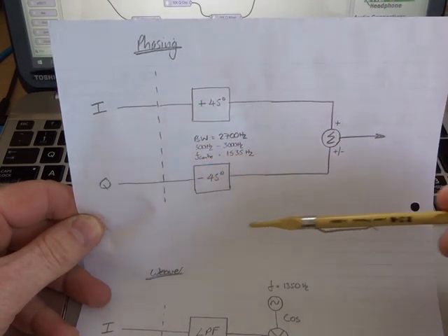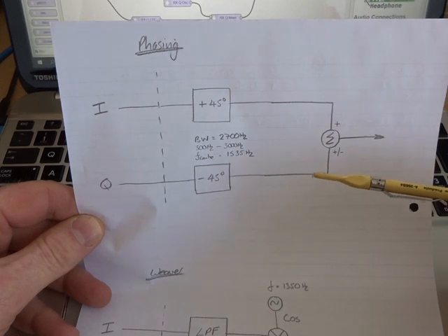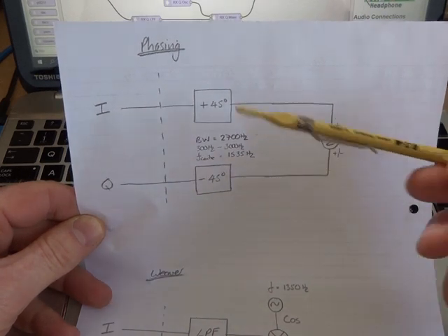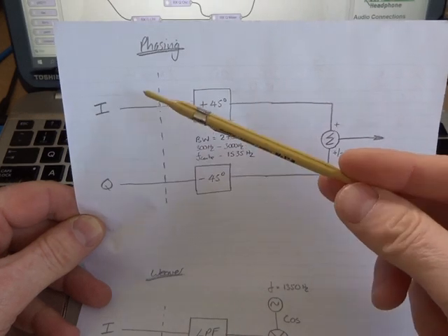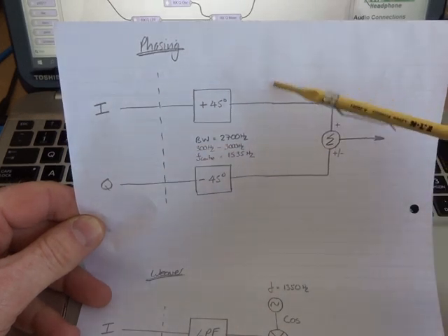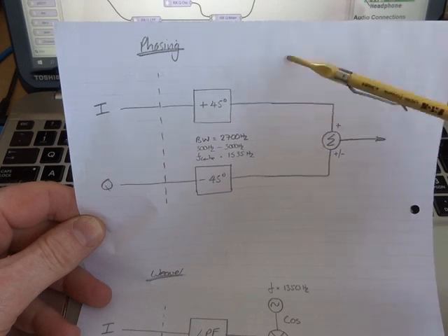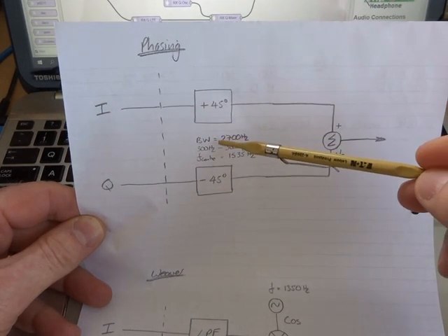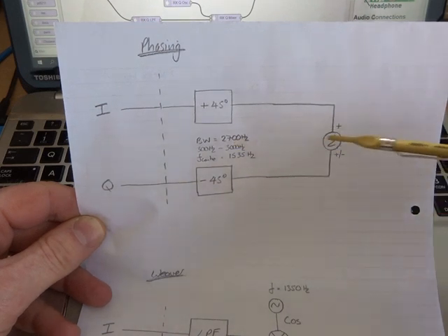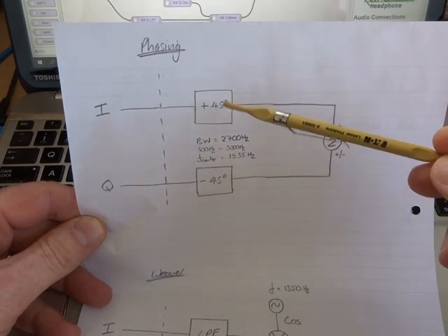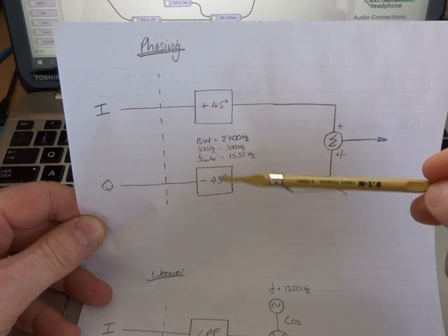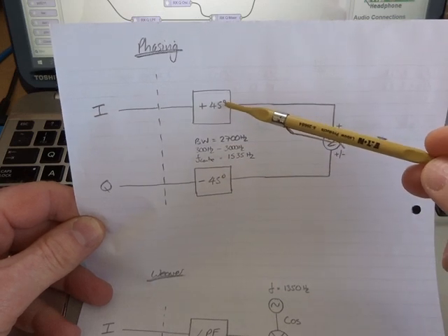If you look at what others have done using the Teensy to do SDR, some have brought the audio in at a much higher frequency, around 10 to 11 kilohertz, and then heterodyned that back down to the audio frequency before punting it out. I've just elected to play around with it at this stage and do the Hilbert transform directly at audio.